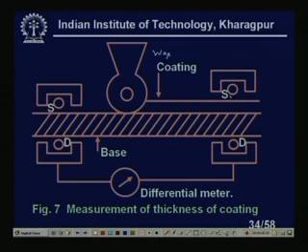So, obviously, you see here, I have a source and a detector, and here I have a source and detector also. It is continuously coming through, and this roll is continuously moving in this direction. Then what will happen? The source and detector will give you some output. I know some predetermined differential output I will get, because this thickness will be very small. So, I need some differential arrangement, so that I will get more deflection or more output, right. That is the reason for this differential arrangement.